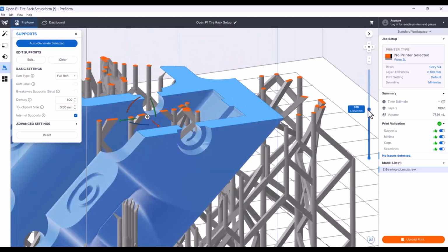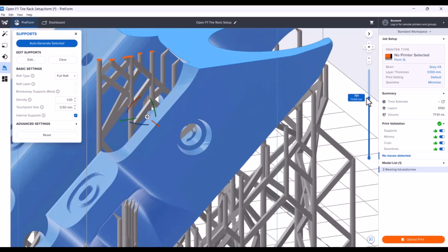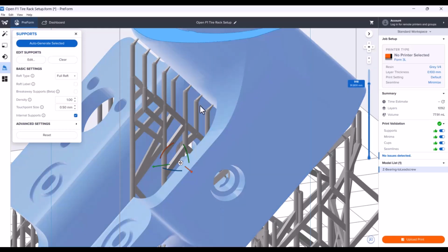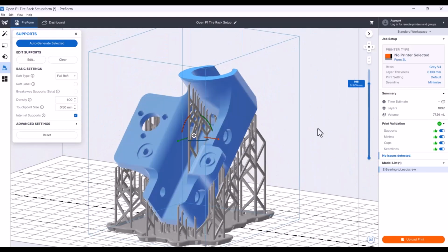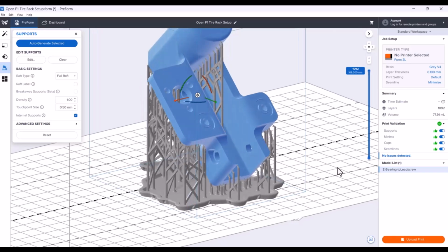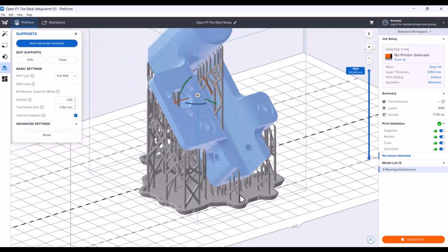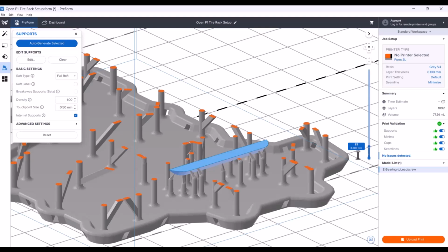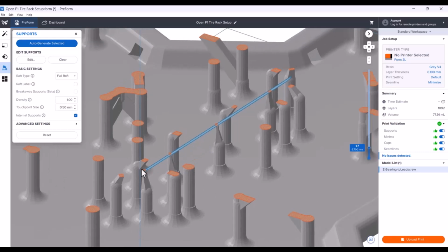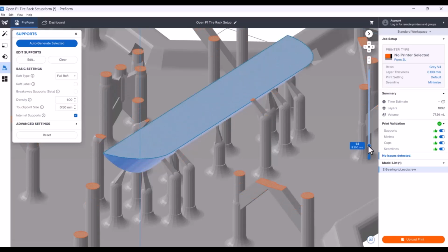Added a spine of supports for this. That might be okay. I think these supports might be a little overkill. I don't really think it's necessary, but then again, it doesn't necessarily hurt to have them there either. Critical thing is right down here at the very start, just making sure that you can see the supports. When you cant something at 45, it has to support on the edge. It's probably one of the only downsides of it.